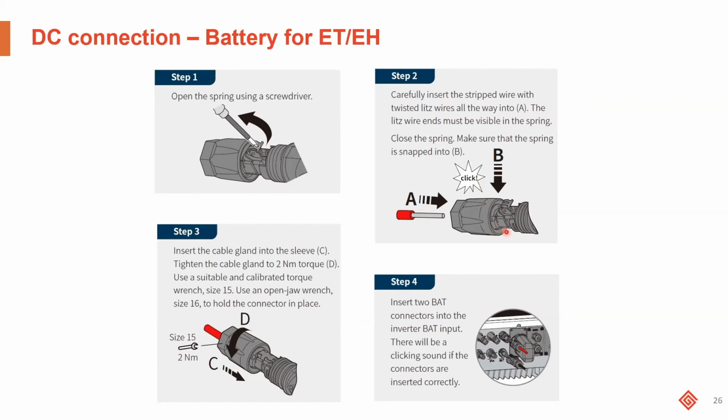With the MC4 connectors, if you do not do the crimping correctly the first time, you have to throw away the connector, recut the cable, restrip the cable, and then redo the process. So every time you get it wrong, you're actually shortening the length of the cable. But with the Sunclix connector, you get 9 chances of getting it right.